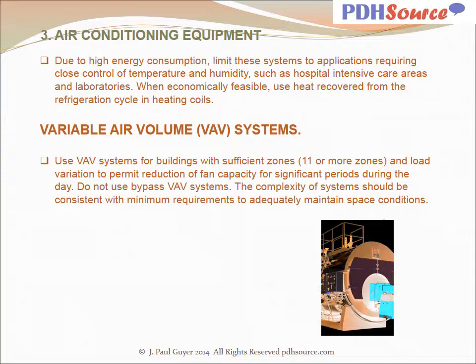Due to high energy consumption, limit these systems to applications requiring close control of temperature and humidity, such as hospital intensive care areas and laboratories. When economically feasible, use heat recovered from the refrigeration cycle in heating coils.